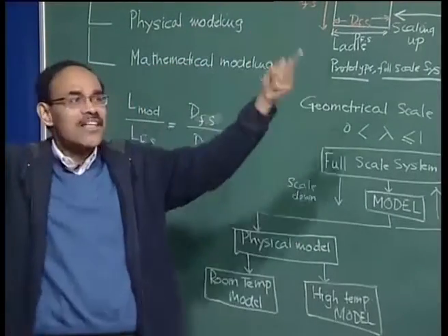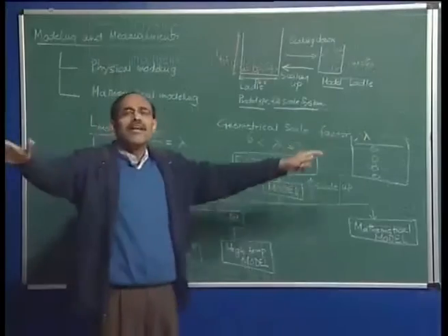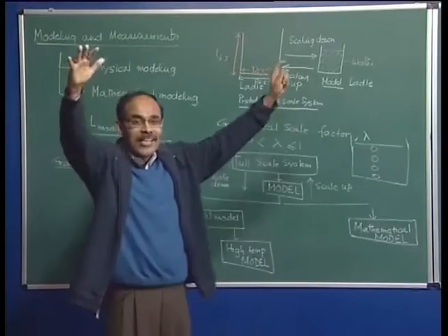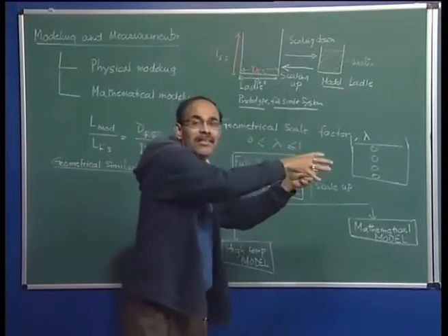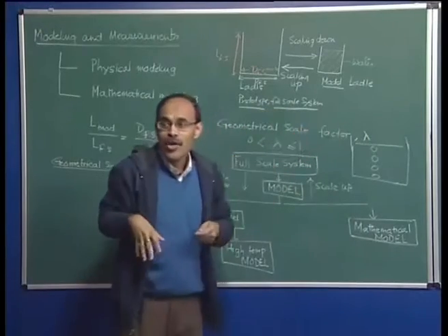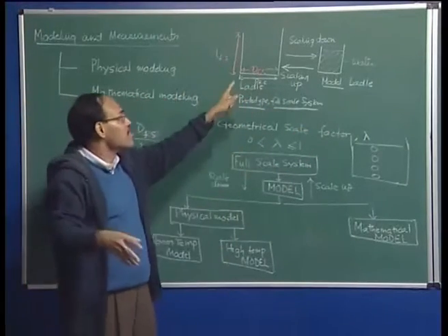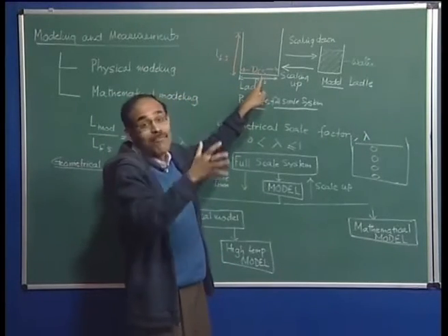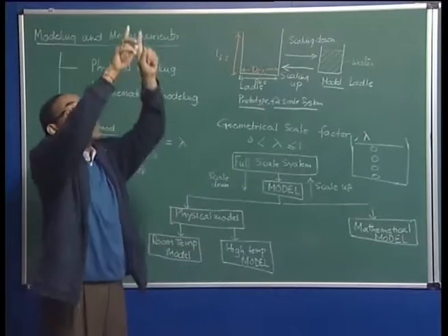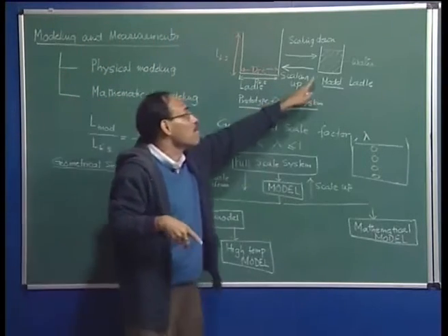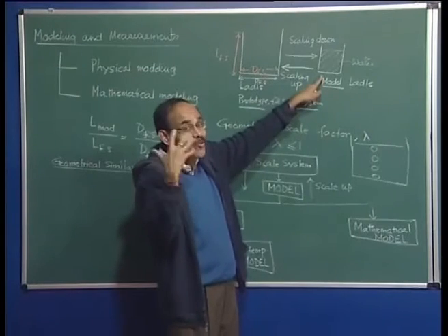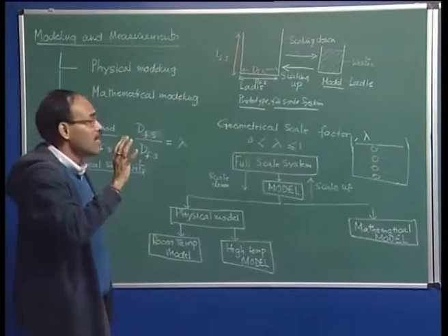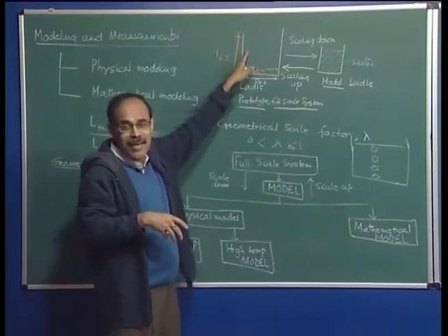So, I have started with a tundish. In the first heat itself, it looks perfectly okay, but as the process goes on, the geometry of the nozzle changes, the lining shape changes, and there may be some skull formation or some solidification. So, the geometry of the actual industrial tundish or the ladle may not be the same all throughout the process. So, taking an engineering drawing of the system and fabricating a model may not truly represent the industrial system itself. So, there may be some element of uncertainty, because of the very nature of the steelmaking process itself.